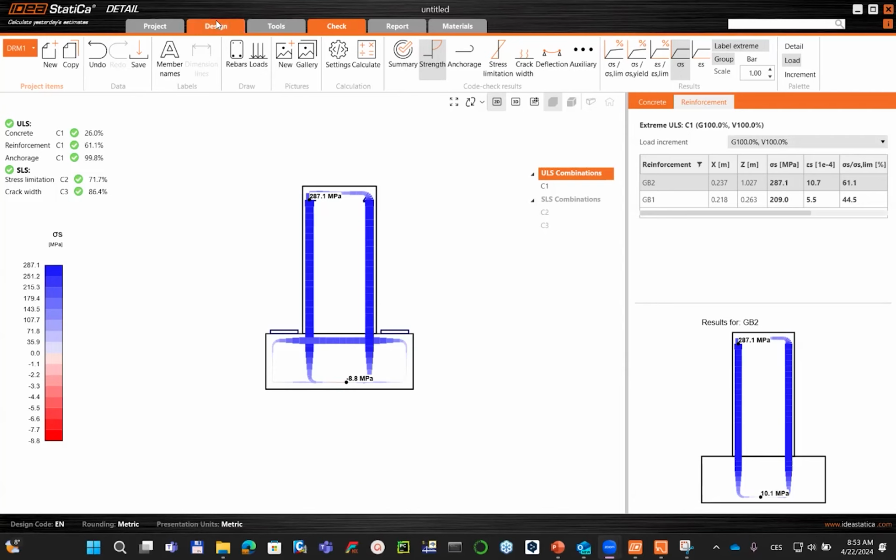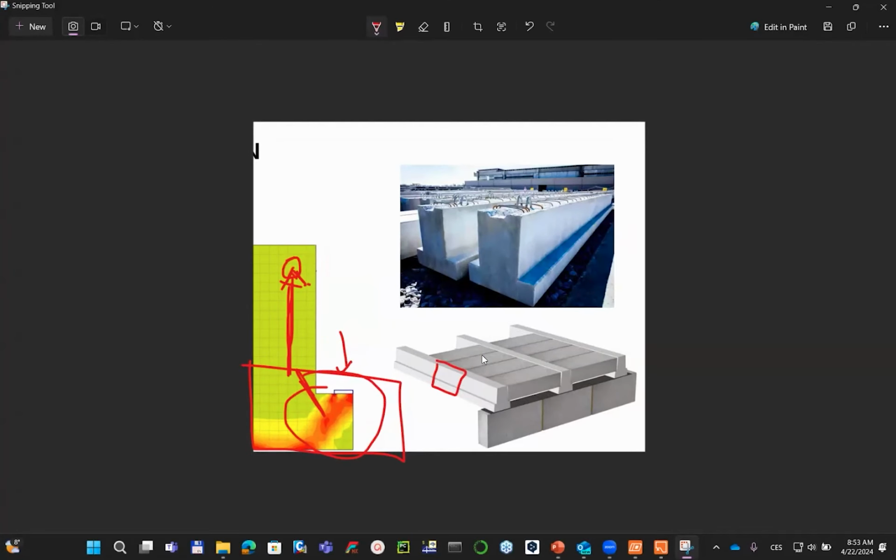Generally, how I draw here, you can expect that this has a 7 meter span, but generally it doesn't matter right now. If you would like to do the code check of the beam in this direction, you will use some beam analogy, put there some stirrups, put there some longitudinal reinforcement and do the code check. For us, the area of interest can be close to the support, or it can be in the middle of the beam. So it's up to you to investigate the beam.